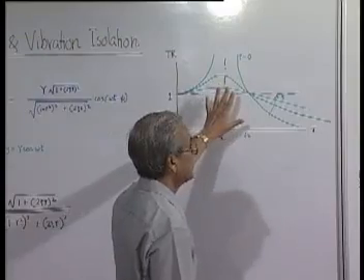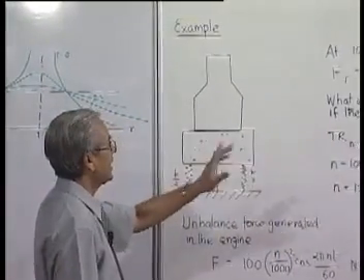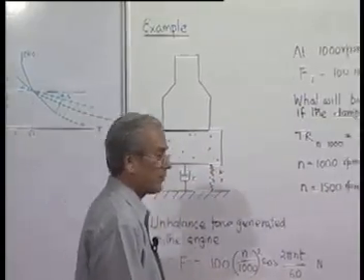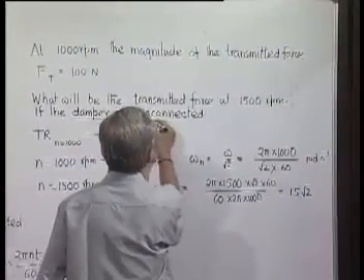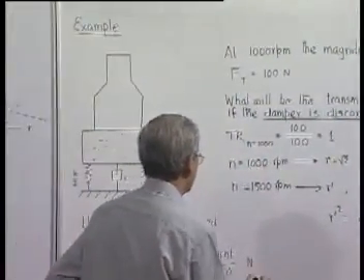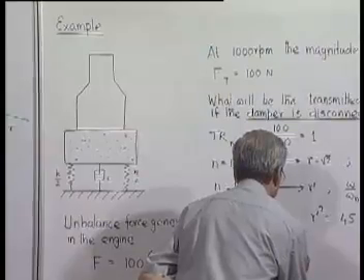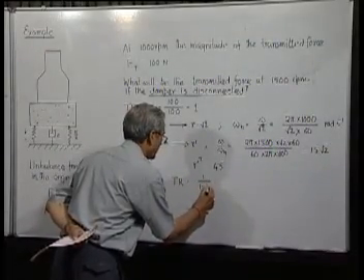But in this case, we have not been given that information. So, what we can find out is the case when the damper is disconnected. In this situation, the transmissibility is given simply by 1 by 1 minus r square.